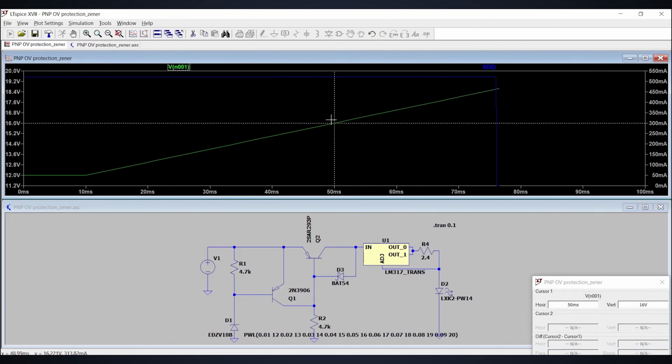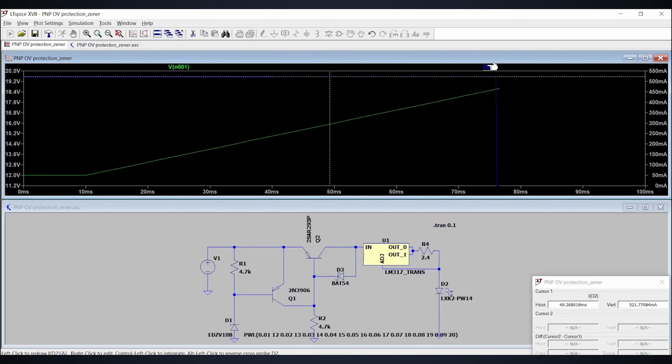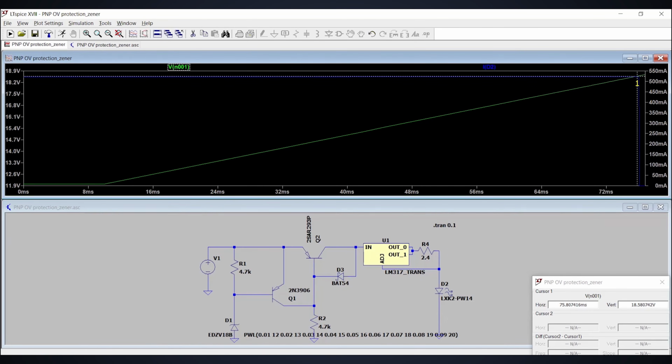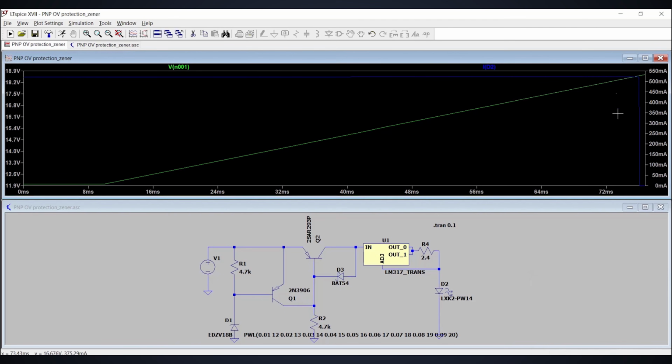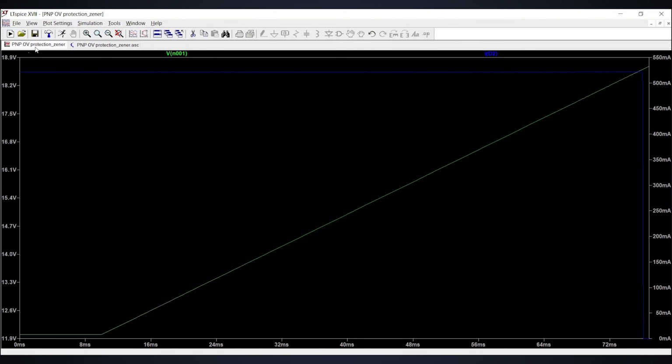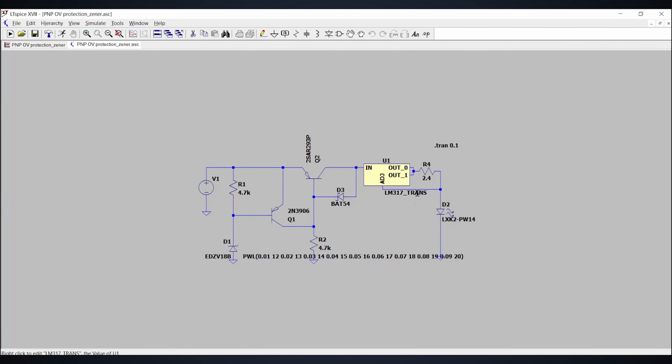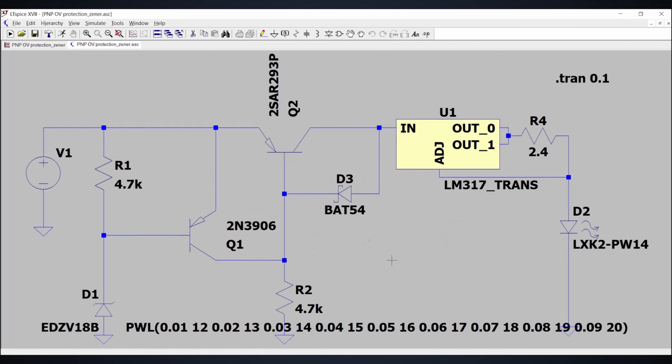the input voltage is rising from 12 volts to 20 volts step by step. 0.5 ampere current flows to the circuit without any disturbance up to around 18.6 volts. And after that, Q2 cuts off the circuit. The Zener diode starts conducting at 18 volts and the remaining 0.6 volts is required to turn on this BJT. Well, in the simulation. But in an actual circuit, this will change a very little bit, and this configuration makes sure that our circuit is well protected from overvoltage.